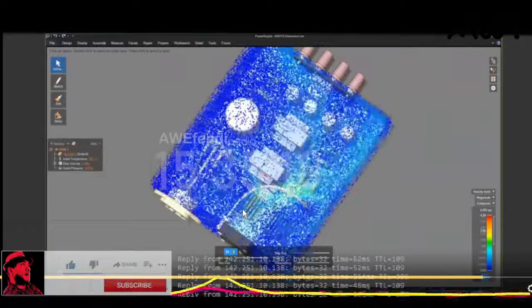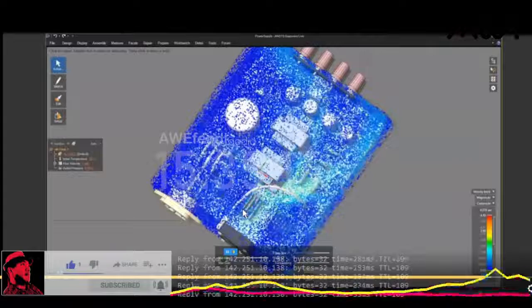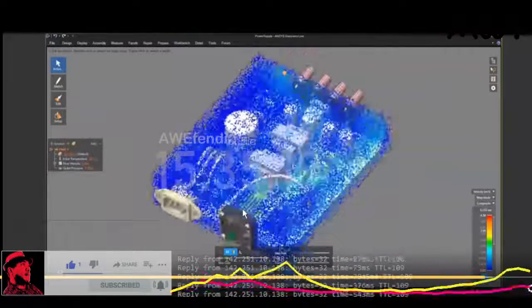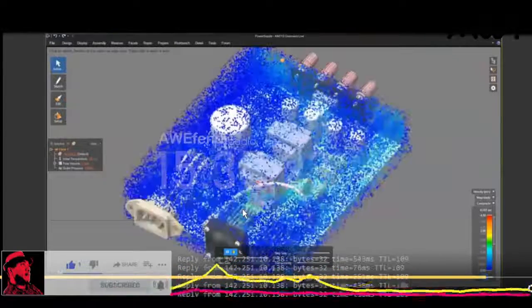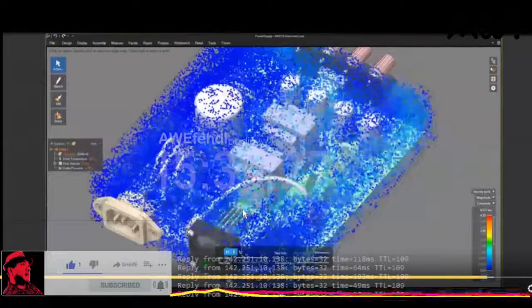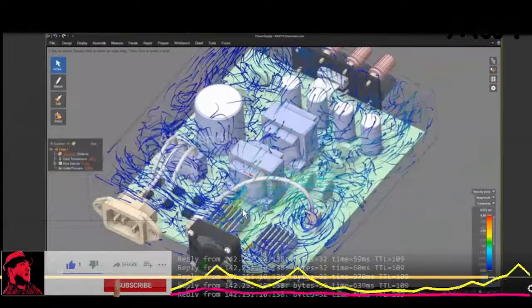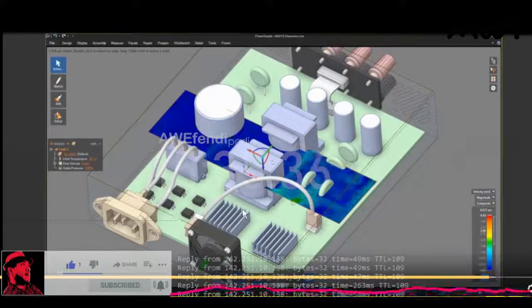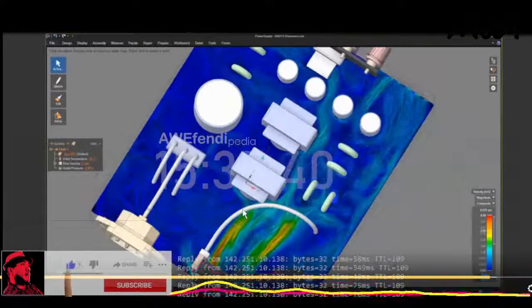A lot of the air is going in this area, and then it hits this, and it goes straight out the exhaust. So a lot of the stuff on the left side or the right side isn't getting the air that it needs, but maybe these components on the left aren't getting as hot as this gray one back here. So I want to just experiment with, what if I just move its location, right? What if I can just shift a couple things there and get more flow there? So that's going to be the thing that I'm going to be interested in doing.